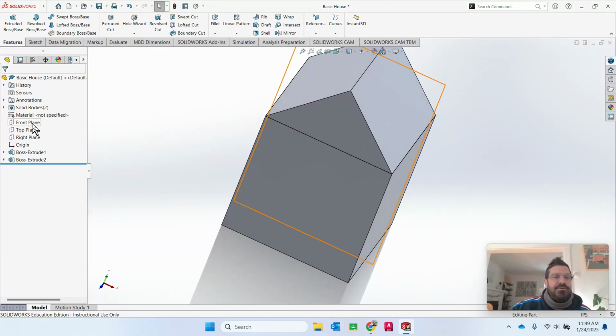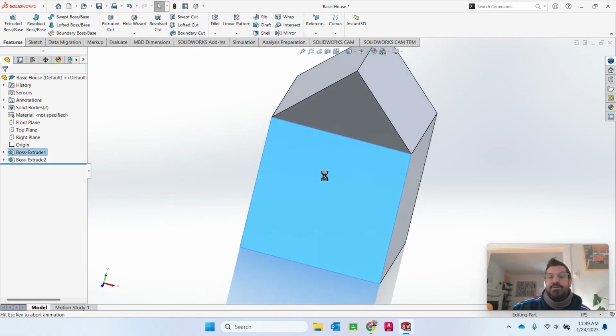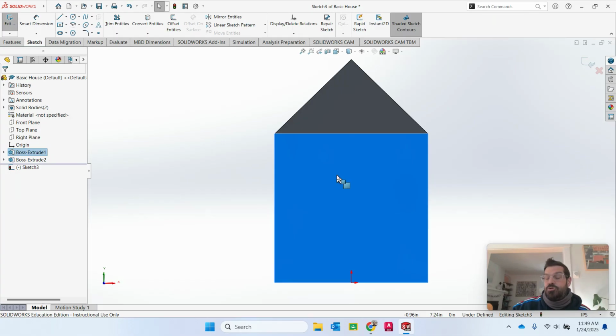And one more thing, I don't always have to make a new sketch on a front plane or a top plane or right plane. If I right click on this face, it's going to ask me what I want to do. I've got a whole bunch of stuff here. I don't want to edit that sketch. I want to make a new sketch. So I right clicked on this face, make a new sketch. It brings me to this side of the house.